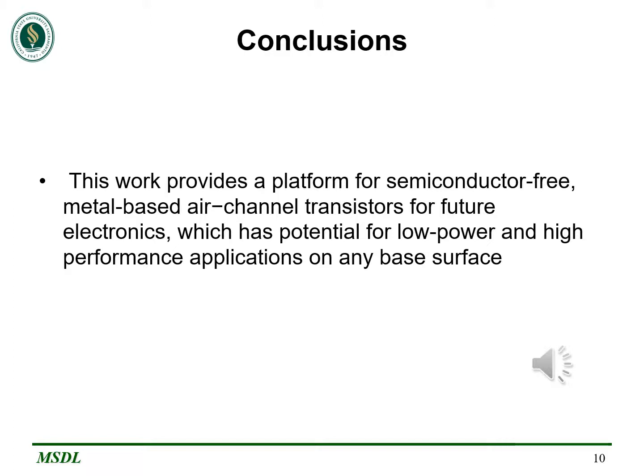Conclusions. In summary, we present a planar point-to-point structure of air channel transistors, fabricated using standard silicon technology. Metal electrodes based on tungsten, gold, and platinum are considered for this analysis. Separation between electrodes is achieved in the range of 11.5 to 36.1 nanometers, which is less than the mean free path of electrons in air, that is, less than 68 nanometers.